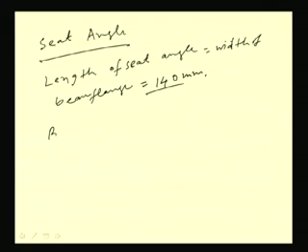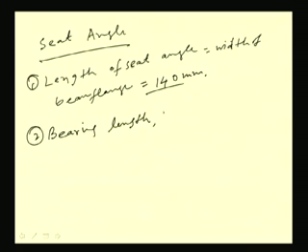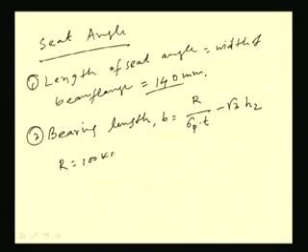Now we have to calculate the bearing length. Next step. So first step is this, second step is bearing length, which is called B, that can be found from this formula: R by sigma P into t, minus root 3 into H2. So if we provide the values, here R is given as 100 kilonewton and sigma P is 0.75 Fy.